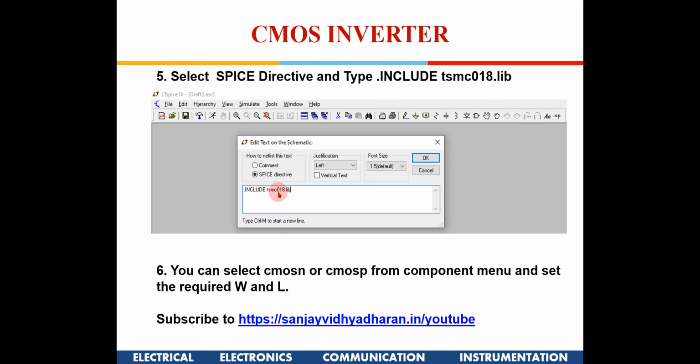This is the name of the spice file which we have pasted, so you have to write .include and the name of the file. Once you do that, you are ready to go. If you click the component button out here, you will be able to get the CMOS N and CMOS P. I'll demonstrate those things to you.